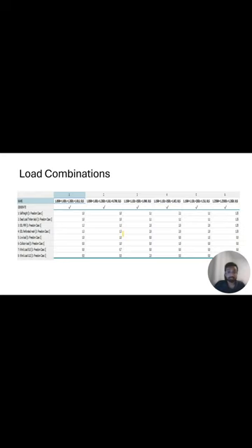Thank you. With the modeling, first of all, we did the linear static modeling, in which we assessed the structural behavior under different loading conditions, and we ensured that deflection and stress remained within the allowable limits. Similarly, we also did the natural frequency model, in which we assessed the vibration impact on the bridge.